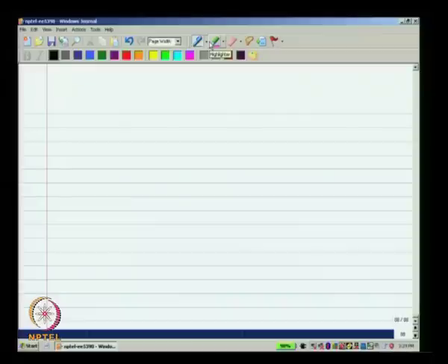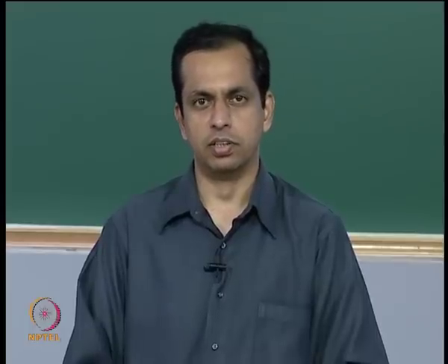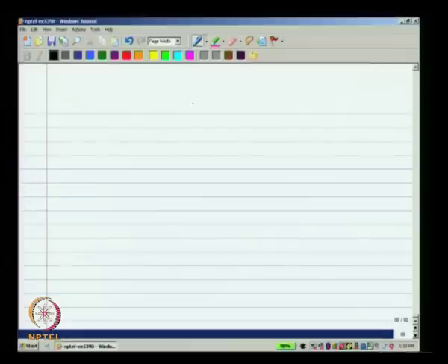So, we have to consider the effect of all 4 terminals on the current in the MOS transistor. We have already looked at the large signal model, and we will use this model as a sort of guideline for our design. Now, it turns out that the actual model of the MOS transistor that reflects the operation of a modern MOS transistor is really complicated. What we will use this very crude model for, the level 0 model, is to gain some insight into the operation of the circuit. Okay. At this point, again let me rewrite the expression for the drain current.